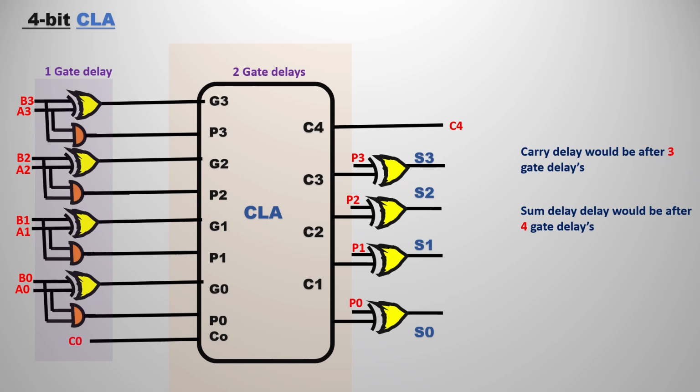If you observe, in the horizontal manner, inside we are passing C0, P0, G0. Same way we can represent it in any manner. These are the only things that we are passing for the carry input. Now we saw those things in the blue, black and red lines. The red line is C0, the blue lines are P0, P1, P2, P3, and the black lines are G0, G1, G2, G3. After passing some operators, we are getting outputs C1, C2, C3, C4. I hope you can relate.